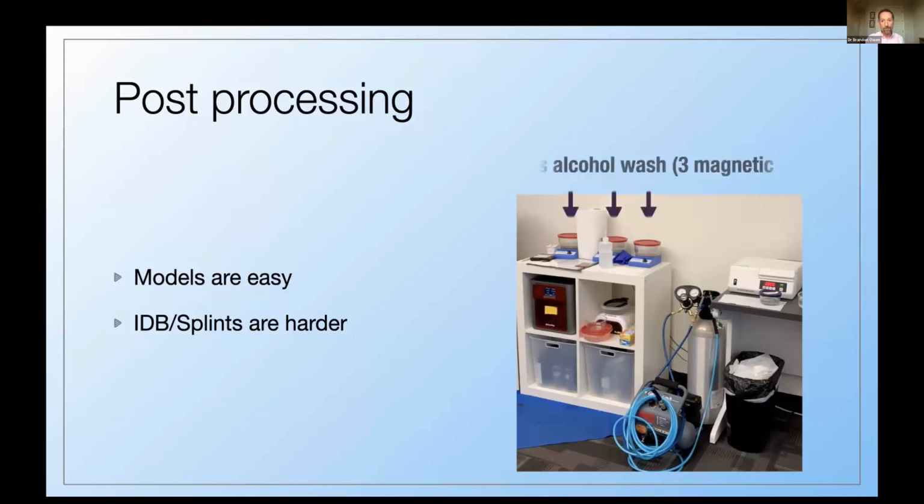And so we typically would go through 3 wash cycles with magnetic stirring plates or oscillators or ultrasonics, whatever you want, using IPA that's at least 92%. We typically are using 99% IPA. After we take it through the various processing, we need to think about keeping all this air. We want to rinse off all the IPA. And this is what's really important: we watch as the evaporation of the IPA is happening. I want to make sure that there's no material flowing across the surface, because IPA, especially at 99%, is just going to evaporate.